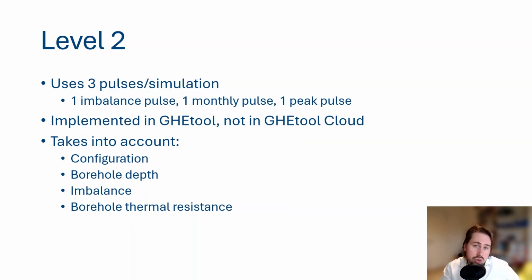And we discussed earlier in the previous video the short-term effects of your borefield, and we said that the peak power is indeed really important. So we take into account this peak power explicitly in this method. But also, and that's the third pulse, the monthly energy exchange in the month in which the peak power occurs.